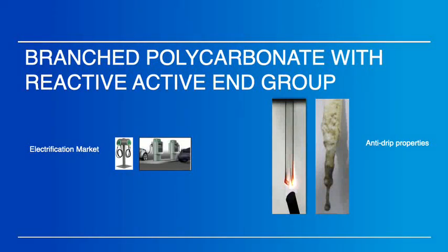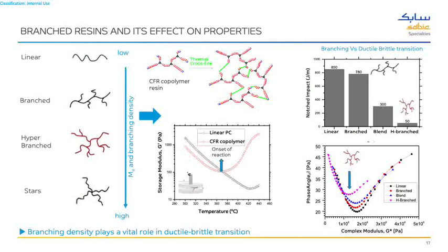So my job here is to tell you how to characterize that material to understand what kind of crosslinking is going on, how you characterize how it flows. For example, here, just to compare, you have a linear material and you can branch it lightly or you can branch it heavily. You can add more end cappers and you can also have a different architecture. So for example, as I told you here, you have the red dots at the backbone, the triangle could be the branching agent, and then there's an end capper. When you go beyond processing, it begins to form a crosslink.